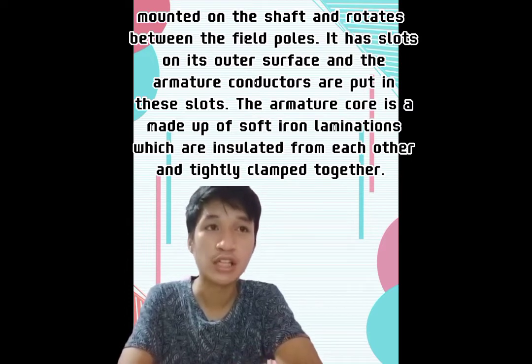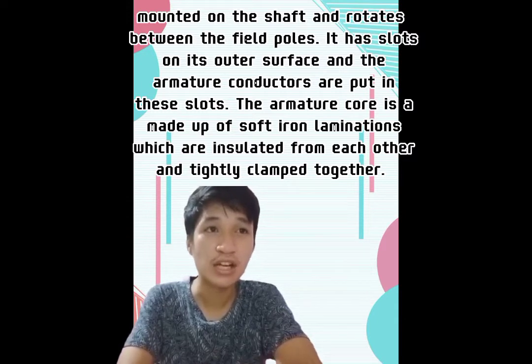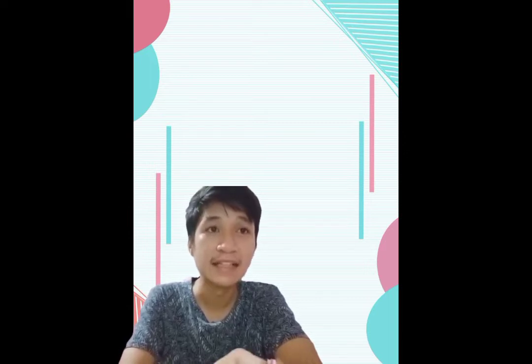The armature core is made up of soft iron laminations which are insulated from each other and tightly clamped together. In small machines the laminations are keyed directly to the shaft, whereas in large machines they are mounted on a spider. The laminated armature core is used to reduce the eddy current loss. But always remember that the armature core is the one that rotates between the field poles.